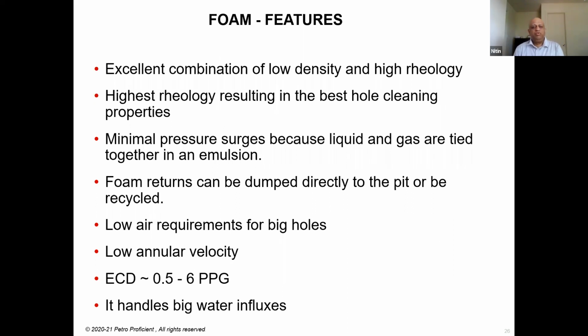So it gives you the best hole cleaning properties, and minimizes pressure surge because liquid and gas are tied together in emulsion. Foam returns can be dumped directly to the pit or can be recycled. Foam can be recycled as well, and it has low air requirements for big holes. Because of the foam's cutting carrying capacity and cutting suspension capacity, because of the viscosity that you now have, you will require lower air than normal air drilling. So foam drilling has its significant advantages.